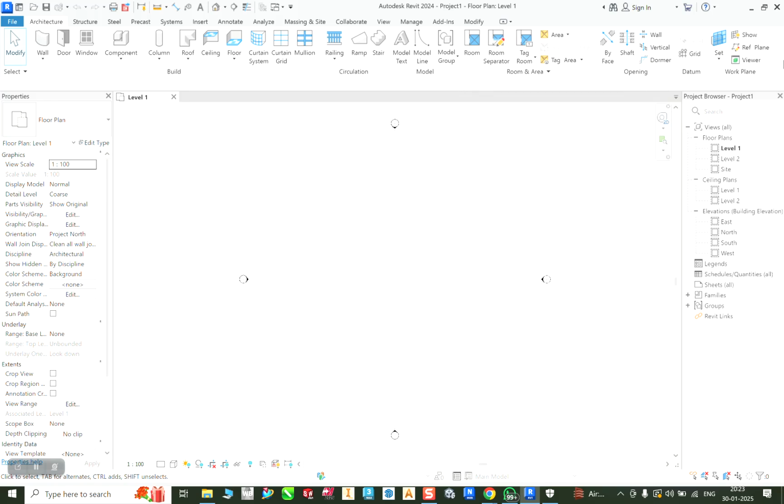So basically all these things are going to be there. These are the openings. When you create walls and want to create some openings between them, these are various types of openings you can use, similar to offset. And here are the planes. These are work planes. If you are working on a warehouse, there are triangular components, so you need to give some angle. You can use these reference planes to create angular bodies, so that your steel cross sections can be assigned to them.